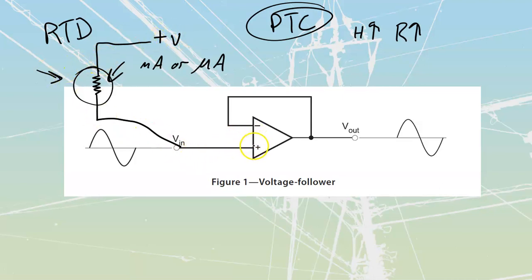Now inside of here, remember we said it's like a voltmeter, which means it's got an extremely high impedance. We're going to place our impedance in here into the range of 200,000, 200k ohms, let's say, for our internal impedance inside of there. That internal impedance does reference through to my voltage positive and my voltage ground. You can go back to that drawing that we saw in the previous learning task.